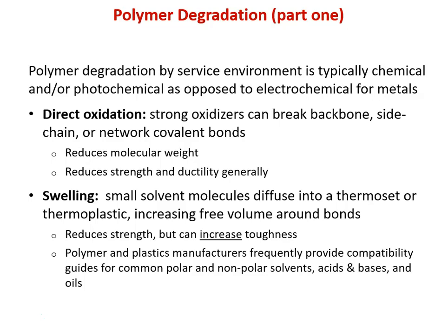Okay, polymers. Wow, they're non-conductive. How are they going to corrode? Well, they corrode their own way. First and foremost, remember most polymers are non-polar, so with the exception of nylons or things that have polar side groups or polar molecules in the main chain, a lot of polymers are non-polar, things like polyethylene, polypropylene. So if we had a non-polar solvent like an oil or something like cyclohexane or an aliphatic hydrocarbon solvent, it might just want to migrate in and sit in there next to those nice non-polar chains.